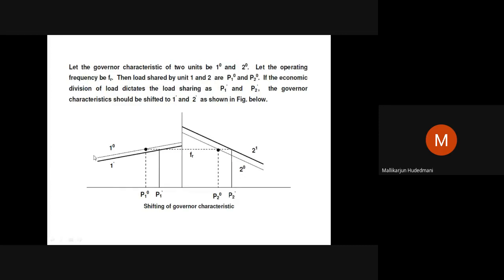Okay. Now, one more general view. This we have already discussed. Suppose I have two generators in a plant. Let's say the solid lines, you can see the grayish, dull line, one, and another line here. They are operating at the rated frequency FR, which intersects at the black dot, and here is the other black dot. The y-axis is the frequency scale, the x-axis is the power scale. Both machines are sharing a certain power, P1 0 and P2 0. So P1 0 plus P2 0 is the demand borne by these two generators to be stable.